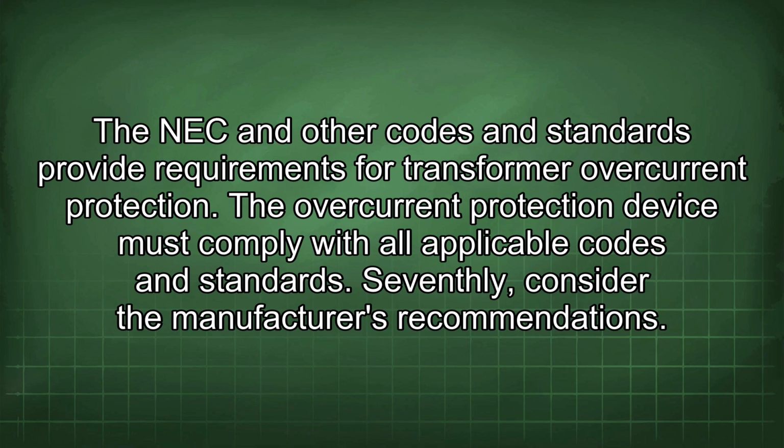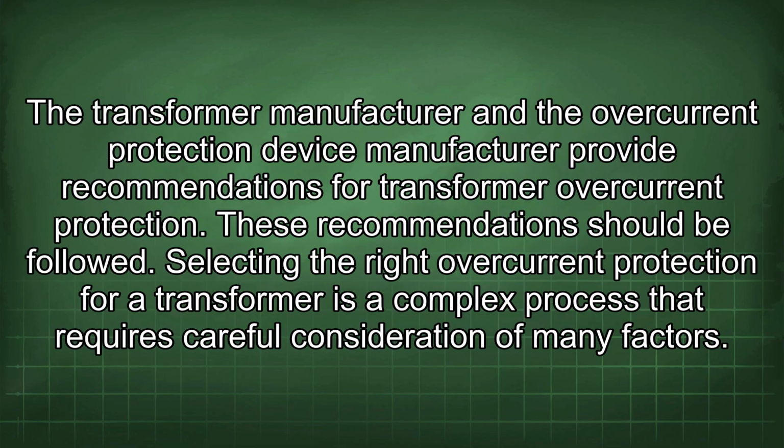The NEC and other codes and standards provide requirements for transformer overcurrent protection. The overcurrent protection device must comply with all applicable codes and standards. Seventhly, consider the manufacturer's recommendations. The transformer manufacturer and the overcurrent protection device manufacturer provide recommendations for transformer overcurrent protection. These recommendations should be followed.